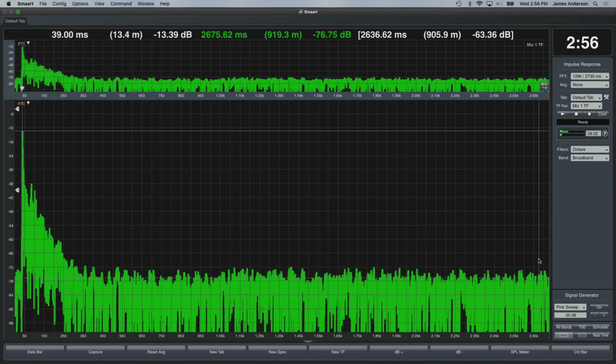Another thing, if you're ever taking a measurement and you've swapped your reference and measurement signal and you take your delay, you might find the impulse at the very end of the record instead of the very beginning. That's a good indication that you've got reference and measurement swapped in your measurement. But without further ado, let's take this measurement, let's do it with a sweep and see what we get.